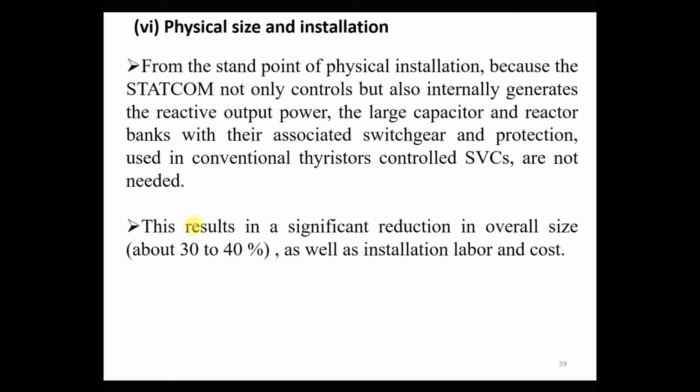Now the sixth point of comparison is physical size and installation. From the standpoint of physical installation, the STATCOM not only controls but also internally generates the reactive power by the voltage source converter, whereas in the SVC large capacitor and reactor banks are required for reactive power injection.